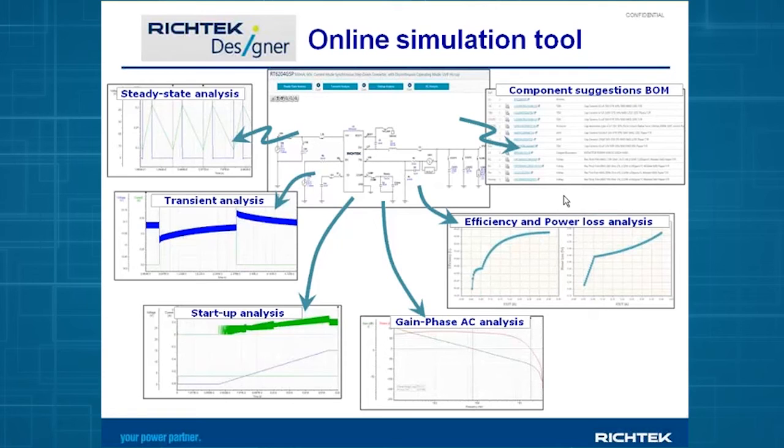So we have taken some care that the component derating effects will not immediately lead to instability problems, but for sure you of course have to check with your own components whether these components are indeed suitable based on DC bias effects, ESR effects, etc.